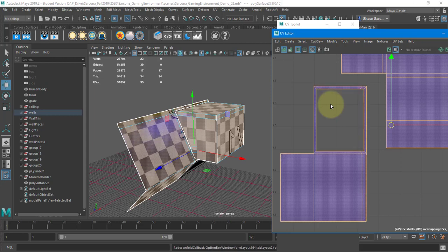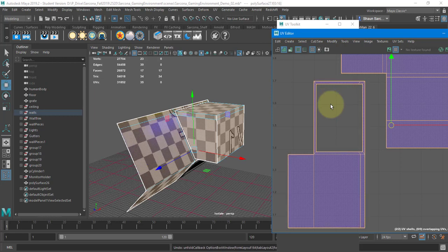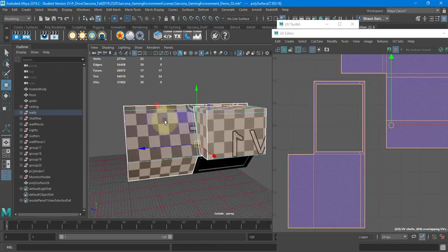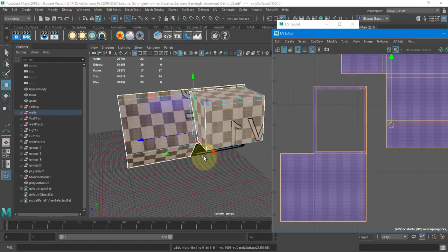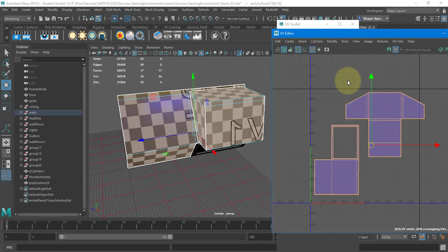Okay, so it looks like we actually did need this a little bit. What it's doing is it's looking at all of the surfaces and trying to keep everything square. That's all it's doing. So it saw that in this shape, even though it looked square on my screen and up here, it was a little bit off. And so that's fixing it. That's making everything look square. So we unfolded. It unfolds everything. And then the second thing we're going to do is layout UV.